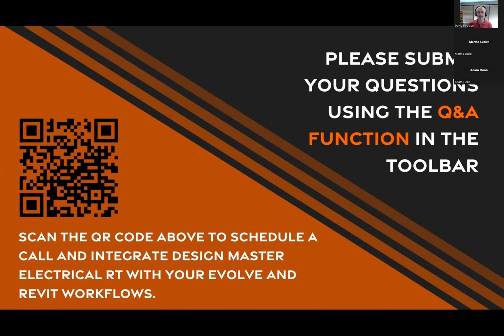But if we move this panel, we will get a new feeder length, and I should make a note of what that feeder length is before I move it. So currently it is seeing 195 feet. If we take this panel and we move it over here, and then we take a look at that panel in the panel edit again, it is now 180 feet. So we moved it in the model and it used that new location to calculate that length.